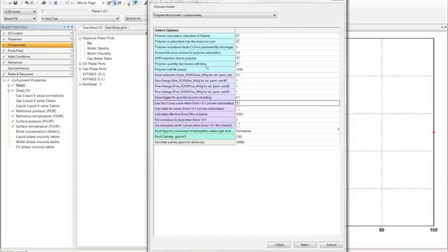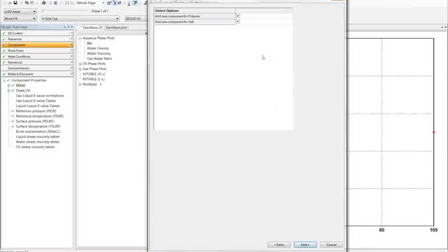Now, another input option here is the polymer degradation. This polymer quantity decreases with time. When you choose that option, it asks for a polymer half-life in terms of days. This one is about 3 years, so a fairly slow degradation, but still there is a degradation. Now what that will do is the wizard will set up a reaction, a first order reaction of polymer just changing to water. So we'll click next here.